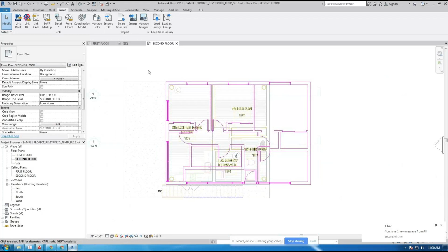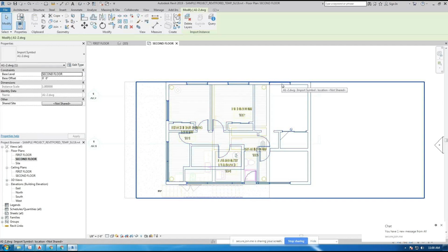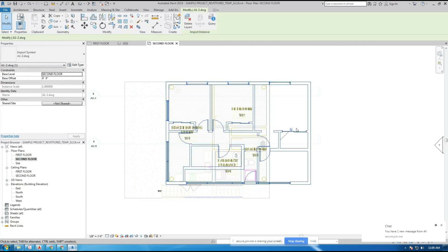what do you do if they don't line up? Well, what I suggest you do is click on the AutoCAD drawing, click on the little pin, or use this command here called the Unpin command, or UP, and move the drawing and line them up. You can line them up using the Align tool, or AL, so they line up together. For example, unpin it here, or UP, or this button. They all do the same thing.